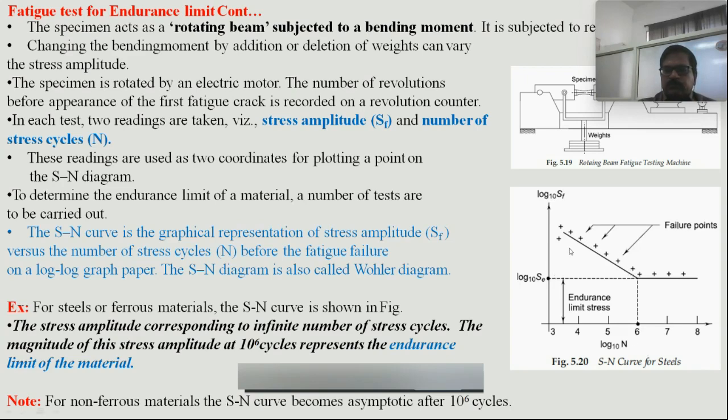And if it is subjected to greater stress values, that is above the endurance limit, the member is going to fail at a lesser number of rotations. So 10 power 6 or more corresponds to the endurance limit, and when the member is subjected to greater stress, the graph is shifted to the left, and thereby you can see the corresponding number of cycles are less.